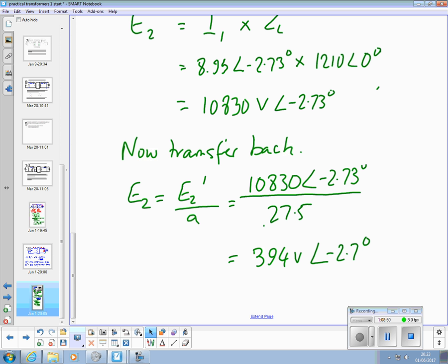The way they'd handle that in design is they'd nudge it with the number of turns on the secondary. On big power step up, step down transformers, you'd select a suitable tapping to get the voltage you wanted at maximum load. They put multiple tappings near the end of the winding, and you use the tapping you want. So there's an adjustment in the design, adjusted on number of turns.